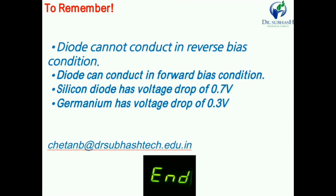Now this slide you have to remember about the diode. First, the diode cannot conduct in reverse bias, and the diode always conducts in forward bias. For silicon it is 0.7 volt, and for germanium it is 0.3 volt. This is called breakdown voltage, knee voltage, barrier potential or breakover voltage. It is 0.7 for silicon and 0.3 for germanium.